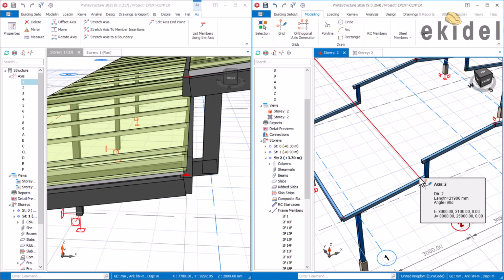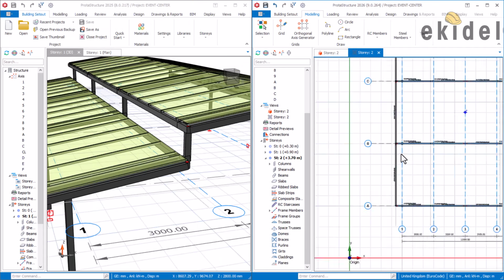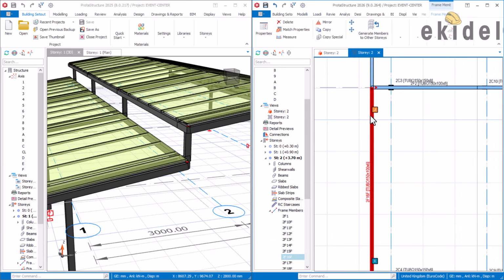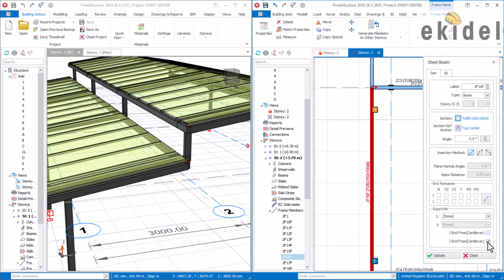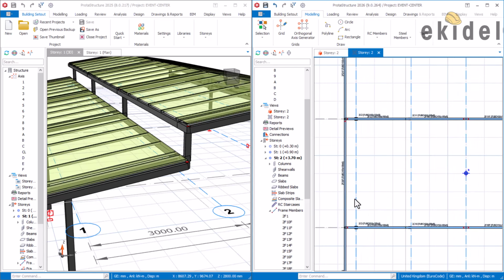Okay, that is fine. So we are going to head back to plan view here, and on the plan view we will make sure that these things are not cantilever. Come here, click here, open it, and we can do this one later by assigning the right end conditions. Okay, update. So make sure we don't have those ones as cantilever. After that we can do those ones.